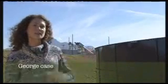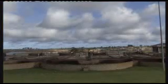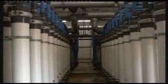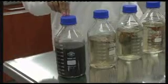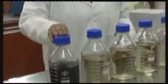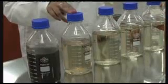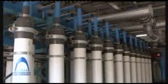Now this plant that's behind us here is the ultrafiltration treatment plant. This effluent goes through the conventional treatment process at the wastewater treatment plant and then through the ultrafiltration plant, where 99.999% of all viruses and bacteria are removed. This is the influent. So whenever you flush your toilets or do the dishes or whatever, that's the water coming into the plant. It then goes to the aeration ditch where oxygen is added and it breaks down the organic matter. This is now the feed that will be used to go into the ultrafiltration plant.